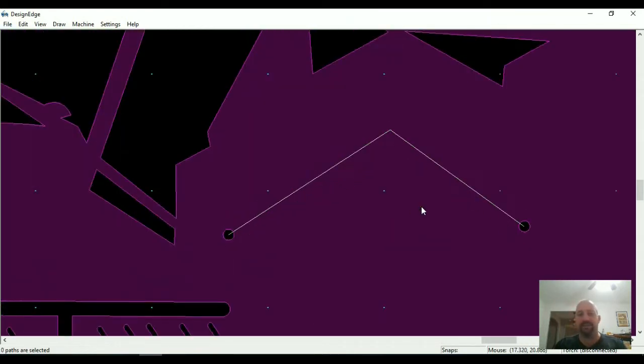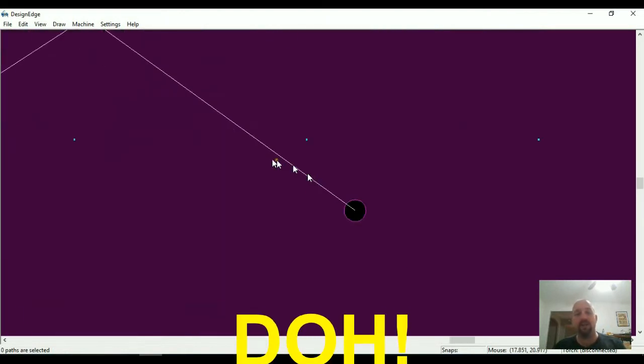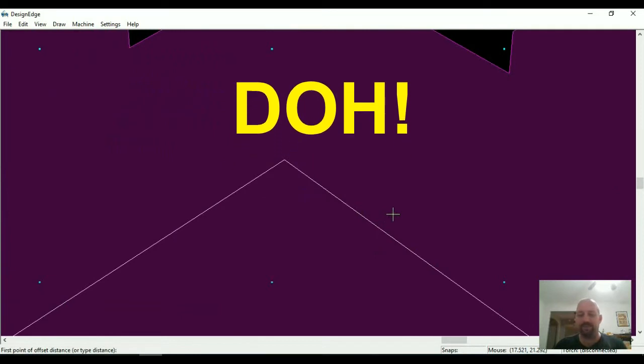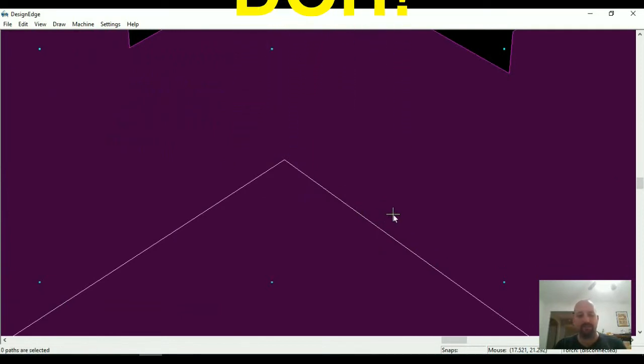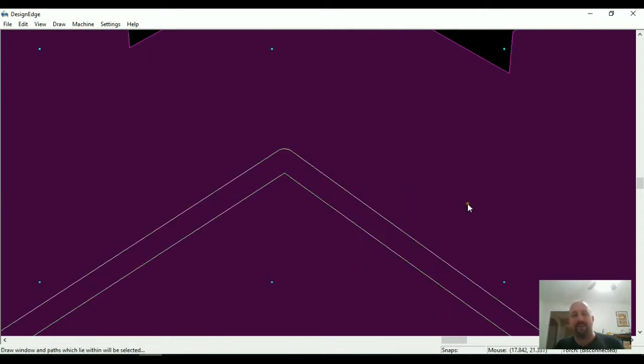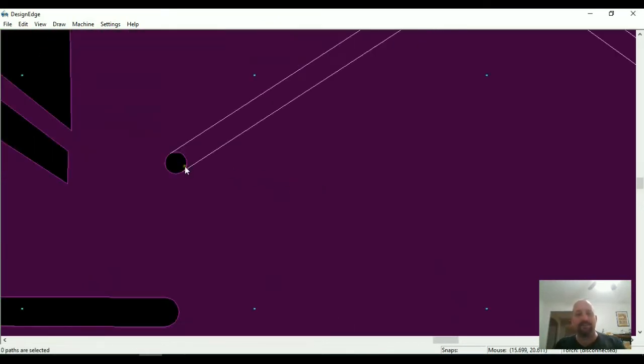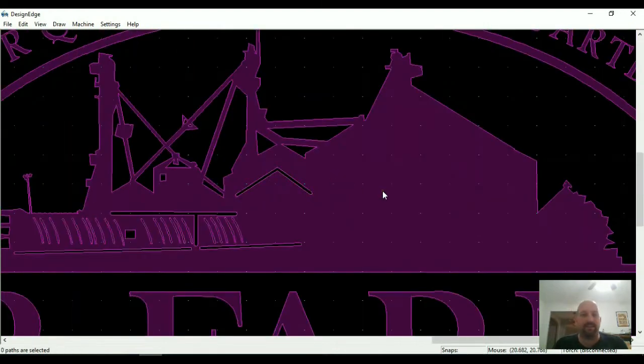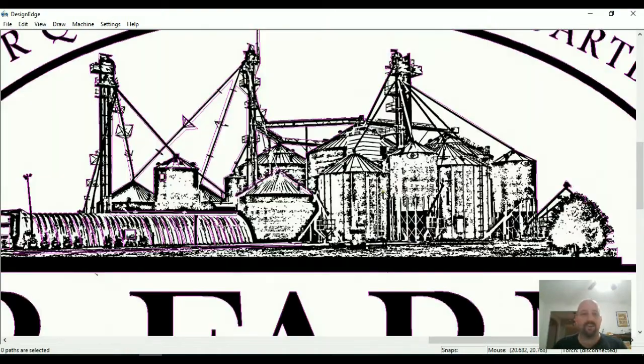And for some reason, oh, it's supposed to be 3/64. So we'll try that again, the smart way. At offset 3/64. There. Now it makes sense. So then we'll X trim these out and J join it, and then there's our other grain elevator.